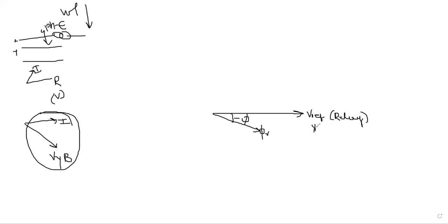Because the fault phase already has a fault, its voltage will dip actually, so we cannot use that. Obviously the current in this case will always be leading this reference voltage. That's why I am drawing the current this way. This is the current, and this is the flux developed by that current, which is at some angle theta, the fault angle.